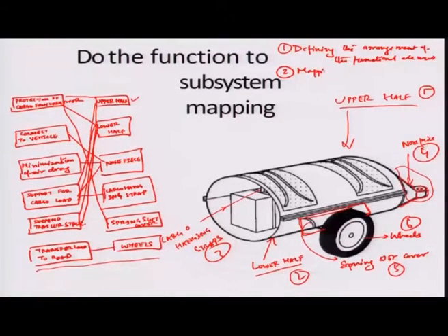We have been doing this for both the examples given in the last slide as well as this slide. So, mapping of functional elements to physical components. And then finally, we define specifications at interfaces of the interacting physical components, and that is how you define the whole product architecture, okay.